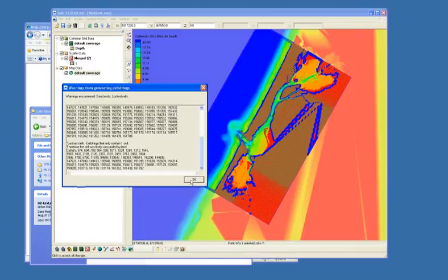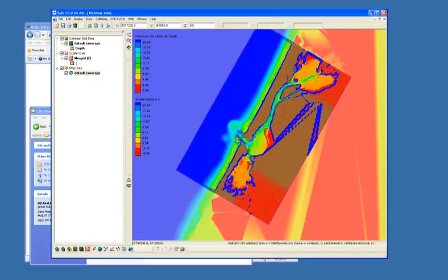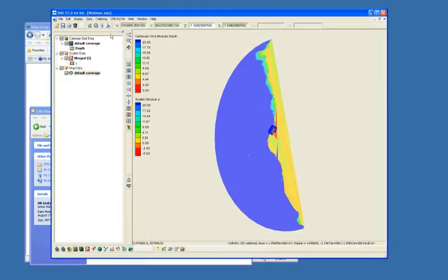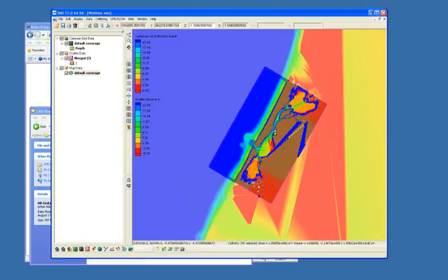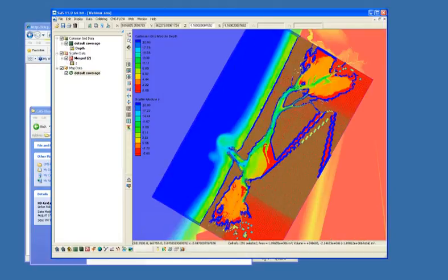if we need to work with these cells, we have our map file. It goes back, and every time you build the grid, it wants to reframe to whatever is showing. So let's zoom in here. I kind of went over some of these modifications. If you want to add resolution, you can do that with new refine points and then regenerate your grid. You'll be working with this several times.